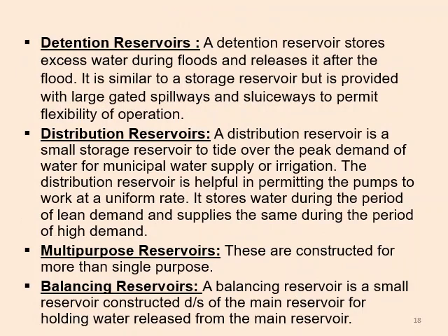Next is the detention reservoir. It stores excess water during a flood and releases it after the flood. It is almost similar to a storage reservoir but is provided with a large gated spillway and sluiceway to permit flexibility in operating the release of water.